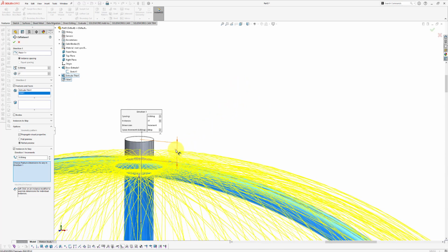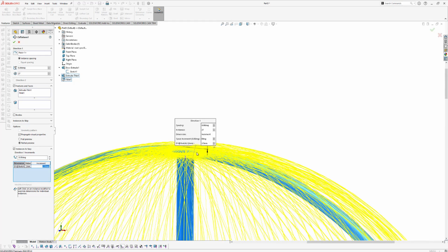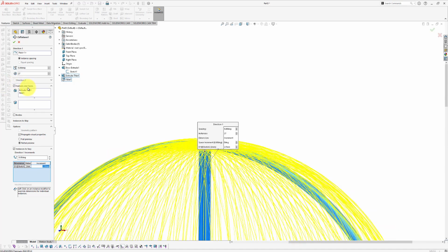And we're going to use this value right here, this 2mm value, to vary. So I'm going to select this one, and we're going to add an increment value to this. We want to make sure that this value is changing 2.5 millimeters with every single body. So we're going to double click at it, type in 2.5, hit enter. And now this will make sure that our circular pattern body is moving 2.5 millimeters with every single body.